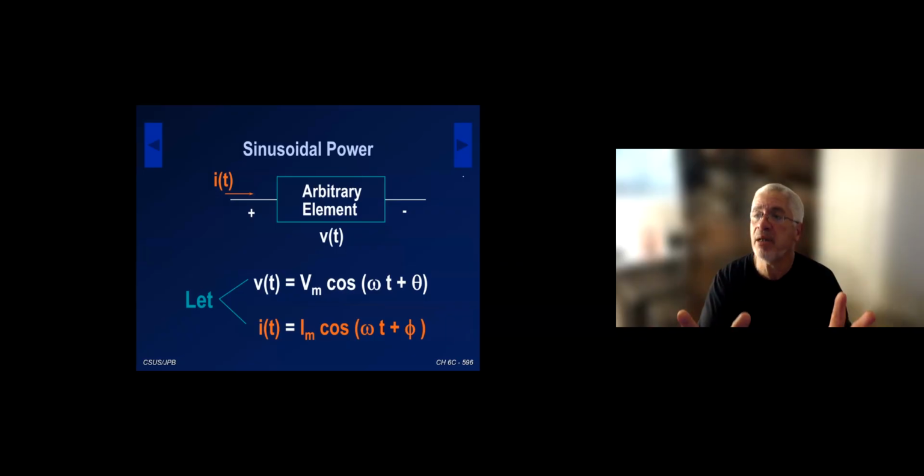The typical nomenclature that we have defined for applying the phasor method. So for the remaining part of this semester, I assume the circuits meet the phasor method requirements that we just talked about. In this particular case, we start by assuming, okay, we have an element. It could also be a piece of circuit, basically. The only thing that you probably should know at this point is that it must be a passive element because the current is entering the positive terminal. So I'm applying the passive sign convention in this, okay?